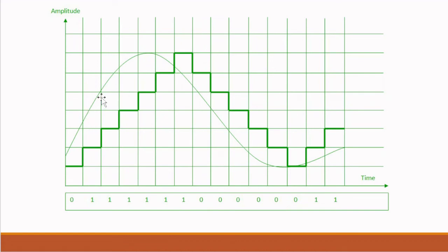Moving forward, we see that our analog signal is still higher than the digital signal, so we still go up the staircase and compare our current state and the previous state. Since the current state is higher than the previous state, we store 1 in our digital data set.